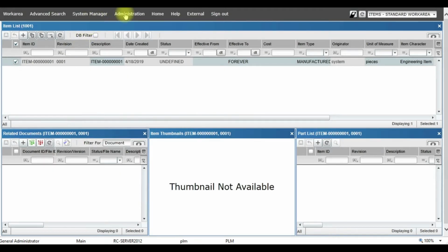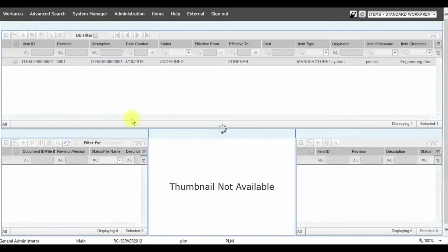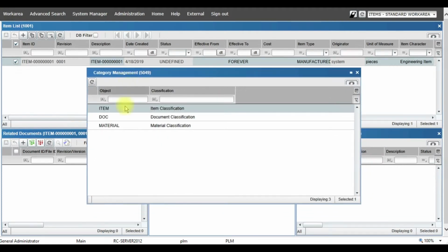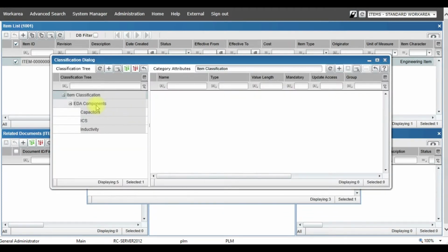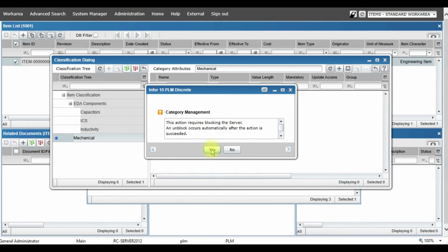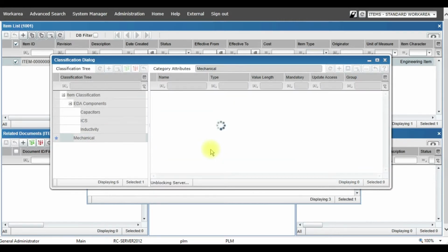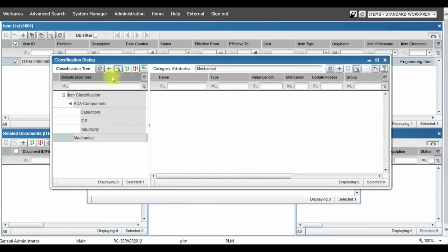In PLM, let's set up each of the attributes based on this screw. We can see that other screws will also fit into the pattern, so this is not a unique part. First, we open the category management from the admin role in PLM. We are concentrating on items, therefore we will select it as well. From here, we will set up the category tree with the various classifications of mechanical, hardware, screws. Each has its logical category level within the confines we have determined.